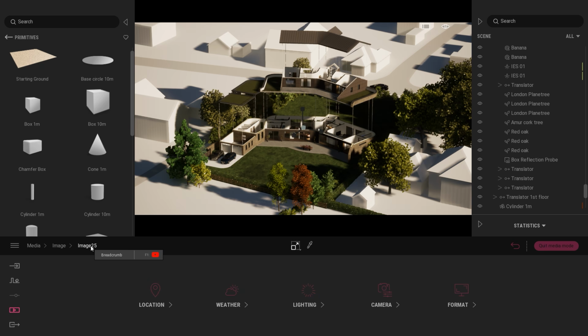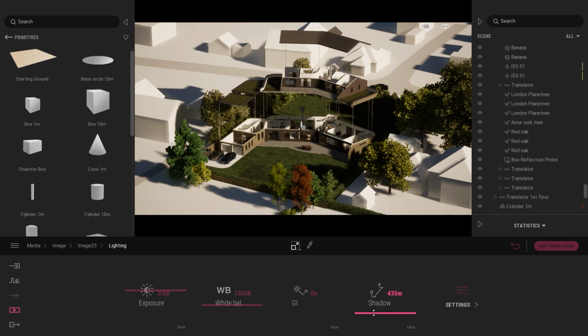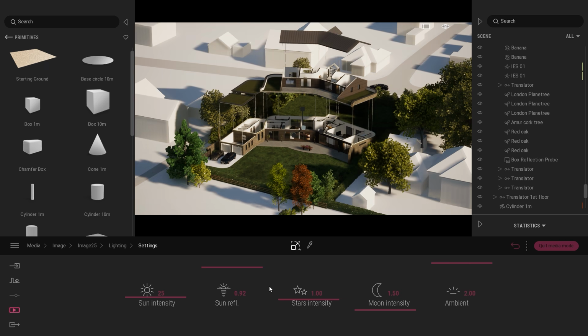Then what I did is also make sure that the shadow is casted long enough. So in some case you can see your project looking like that. It's because you need to move the camera far away to have a really small focal. And sometimes the shadow distance is not casted long enough, so you need to manually change this value. So here 400 meters was fine. And what I also like to do in this kind of render is just change the ambient lighting just so your project has less dark shadow, and changing maybe a bit the white balance to have a bit of a yellowish tint.